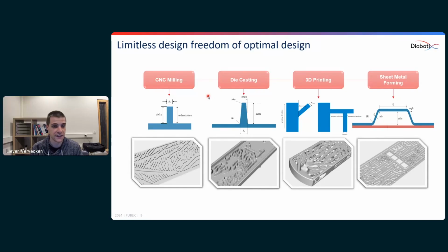And then, of course, the manufacturing settings. As I mentioned before, 3D printing is quite costly for mass manufacturing. It gives the most design flexibility, while more conventional techniques like die casting or sheet metal forming are much cheaper, but they don't offer as much flexibility. And the positive thing with generative design software in general is that you can fine-tune the settings to make sure that whatever the generative design software attempts or creates will meet your manufacturing techniques.